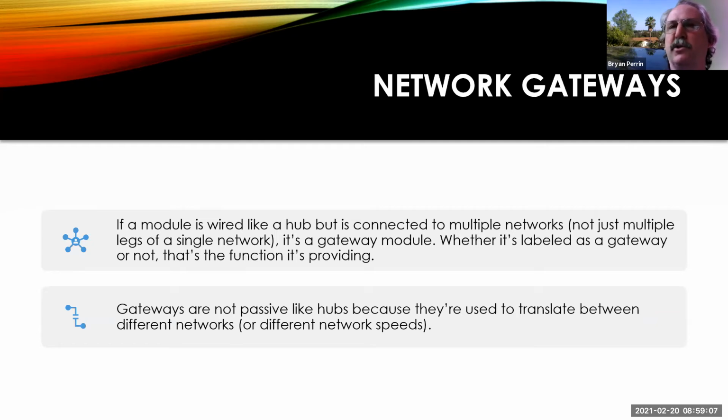Hard to believe, manufacturers figured out that maybe that's not the best idea for a couple of reasons. One is redundancy, obviously. The other is, why should I have an HVAC module, for example, that I want to have on a high-speed network and a medium-speed network? Well, if I put it on the medium-speed network, it needs to go through the gateway to talk to the high-speed network. And if I put it on the high-speed network, it's more expensive and needs to talk to the gateway on the low-speed network. So let it talk to both networks, because it has things it needs to do with people on both networks. Cuts down the traffic through the main gateway module, and it can act as a backup gateway module in case the main one goes down.